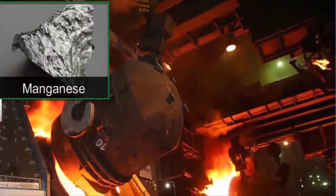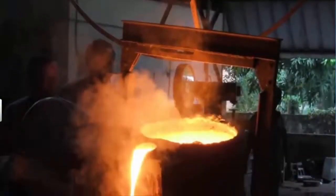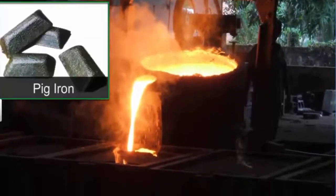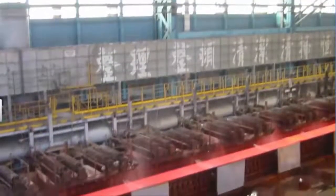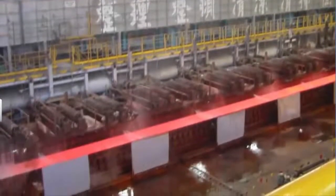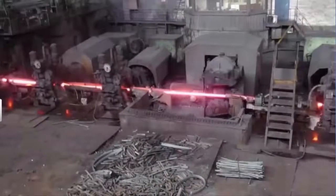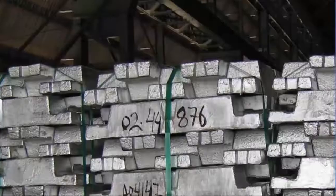Molten iron from the blast furnace is poured into mold called pigs to produce pig iron. Pig iron is melted, purified and alloyed with metals like manganese, nickel and chromium to produce steel. Molten steel is rolled, pressed, cast and shaped into ingots of the desired shape and size. This steel is supplied to other manufacturing industries.